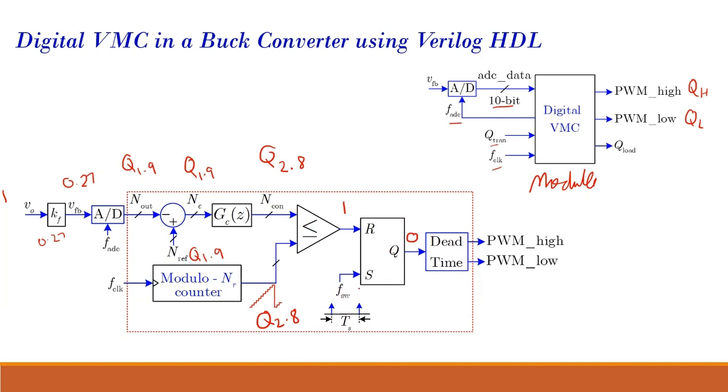And this is periodically set over here, and after a fixed frequency, another pulse comes. So this signal also we must generate. And this is how we are generating our high side PWM as well as my low side signal. Okay, there is a sort of dead time. This time is known as my dead time.